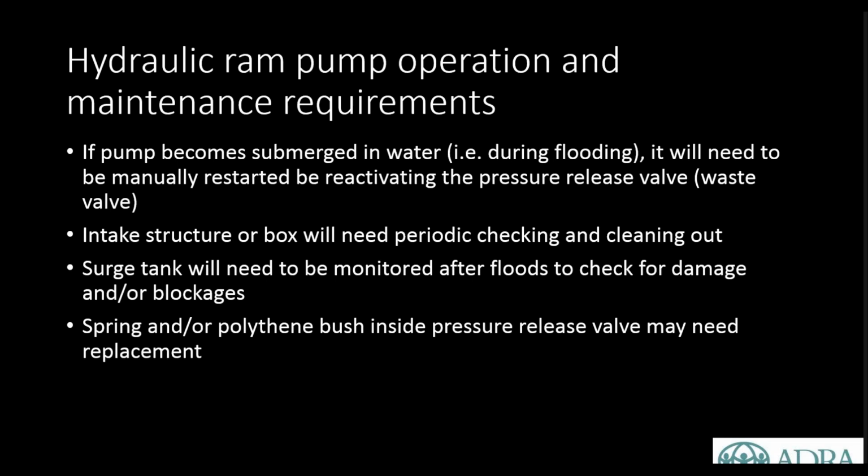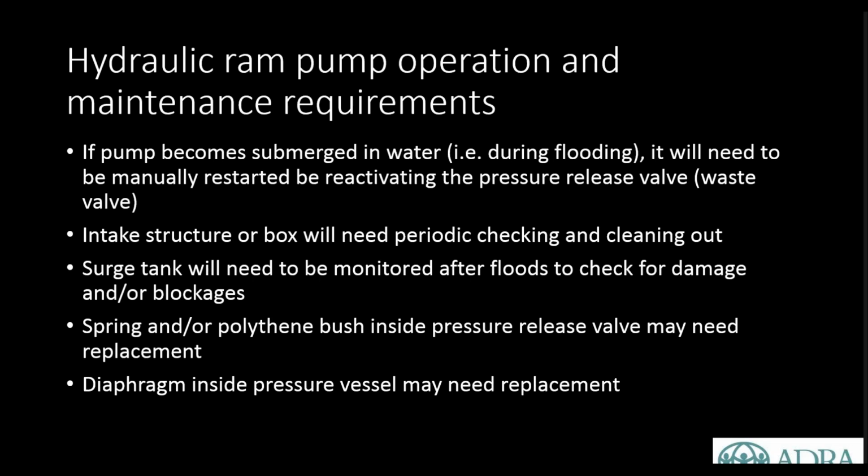There's a spring and a polythene bush inside that pressure release valve where all of the water was pouring out, and that's subject to quite a lot of pressure, and that may need to be replaced as well. The springs are about 12 or 15 millimetres, like the gauge of the actual spring metal is about 12 or 15 millimetres in diameter. So they're quite heavy duty, and the actual spring itself would be about 150 millimetres in diameter. So they're quite a substantial spring, but they still may need to be replaced.